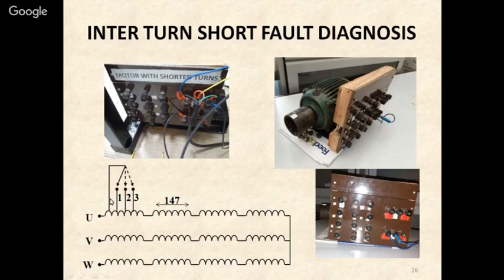So we have made some special tappings out of this phase, and here we can short these turns so that we can artificially create an inter-turn short circuit fault in the motor. After creating this fault, we will acquire the signal from the motor terminals, and then we will be able to diagnose the inter-turn short circuit fault.